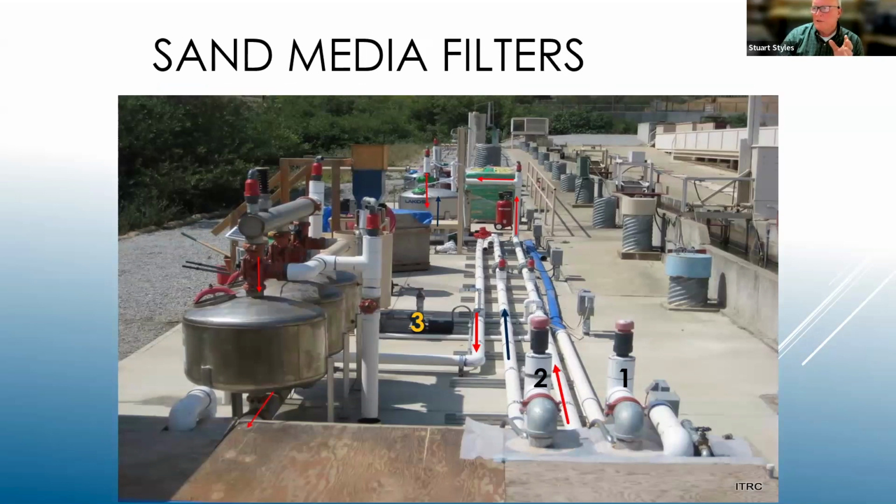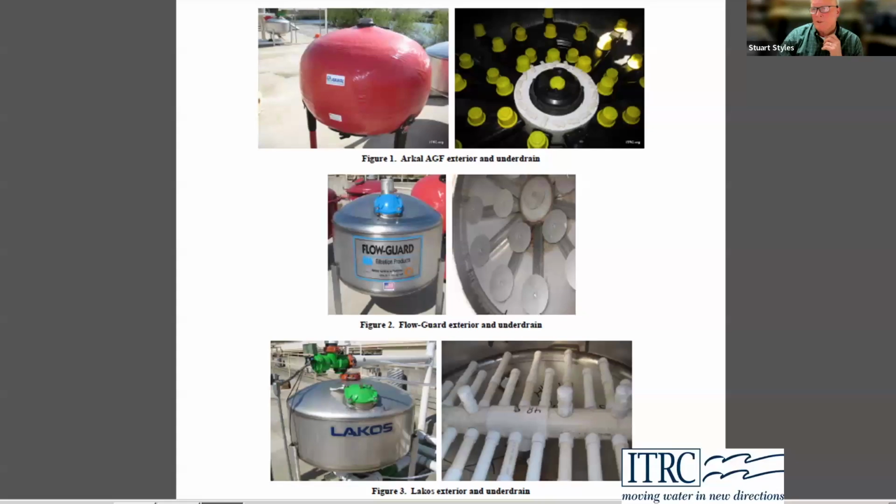A lot of the folks on the Central Coast don't have them. They use the screen filters, and the reason is typically because they have really clean water. But if you have any kind of reservoir, if you're storing the water and then pumping out of a reservoir, you're going to get exposed to a lot of algae, a lot of floating debris potentially, and you typically would have to go to a sand media filter option.